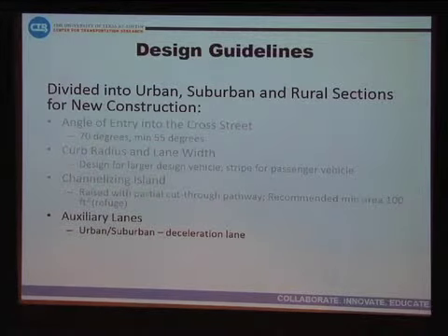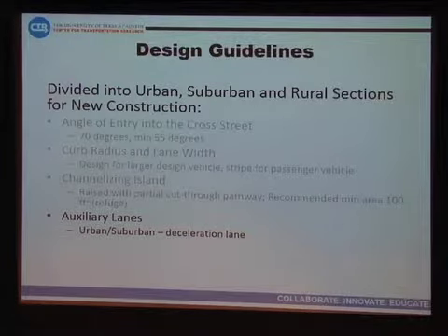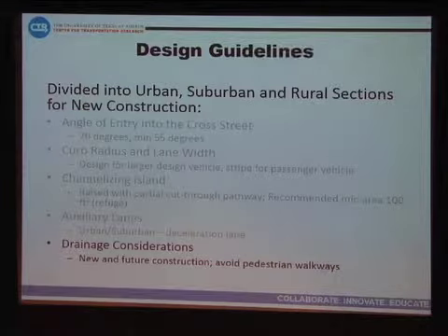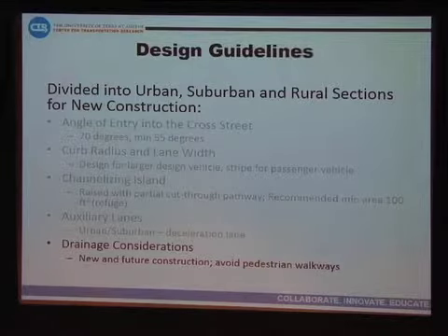With respect to auxiliary lanes, we largely defaulted to input from the roadway design manual on that, where recommendations are provided with respect to deceleration lanes and acceleration lanes, and more or less recommending not to use acceleration lanes in urban and suburban settings where you don't necessarily want high-speed turns and you're more likely to have pedestrians crossing the roadway. We added some sections on drainage considerations for new and future construction to try to avoid conflict with pedestrian facilities and walkways.